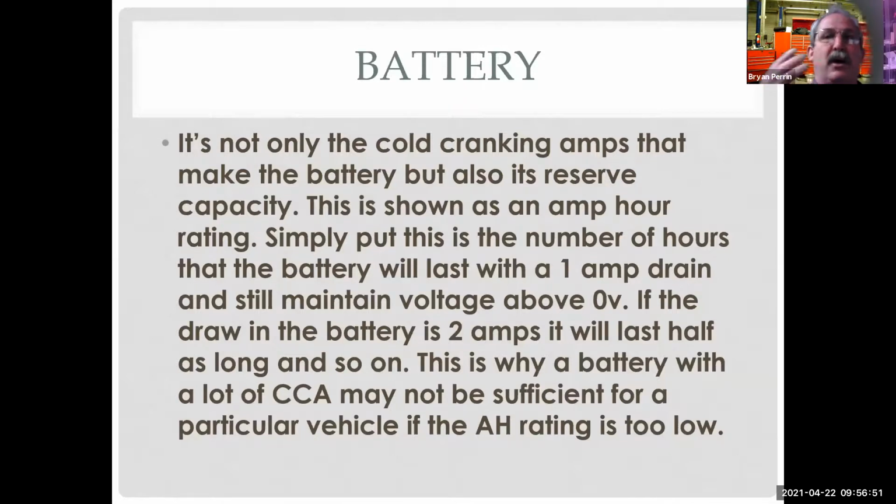And this depends on how many accessories the car has. How many things are drawing power out of the vehicle when the key's off? How long do we expect our vehicle to be able to stay parked in one place, with no one going out and starting it, and have the car still start? So based on these decisions, manufacturers have a recommendation for how many amp hours the battery should have.